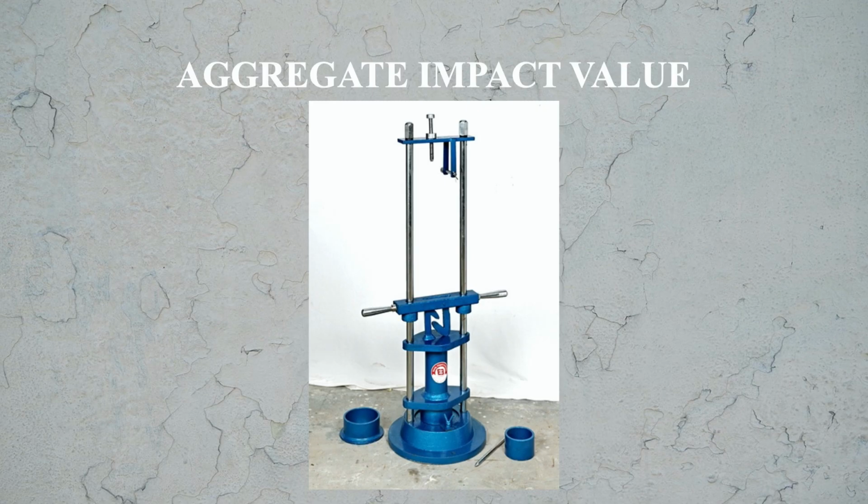So this will be giving impact, and the effect of impact will be crushing of some sample, breaking of some sample. Then we take the sample out and do the sieving and find the impact value as I told you. So that way we do the impact value test.